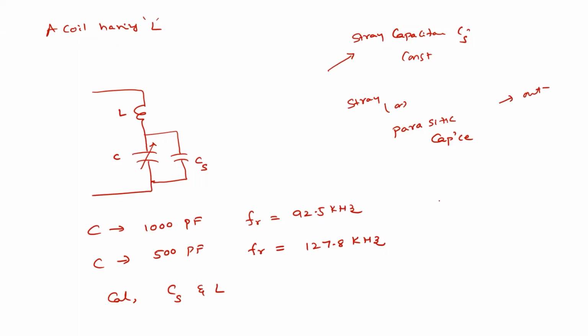For example, when you model a diode, the diode is put in some case, with semiconductor material inside. Between that semiconductor material and the case you have some capacitance, known as stray or parasitic capacitance. So when modeling diodes, we normally assume this capacitance is in parallel with the diode.